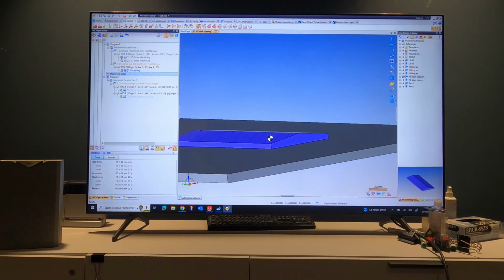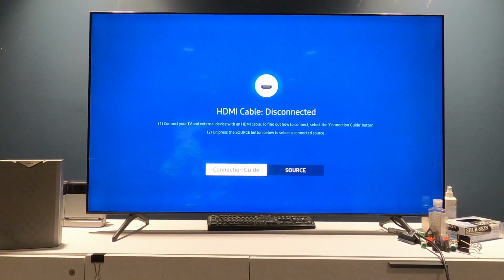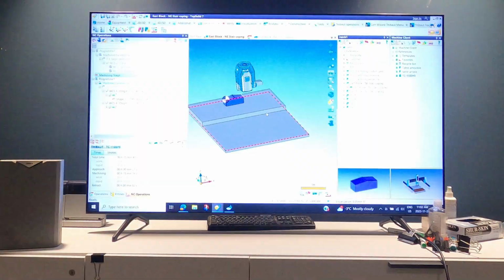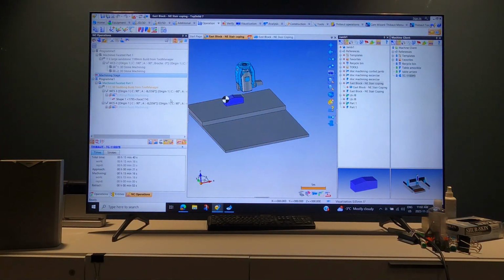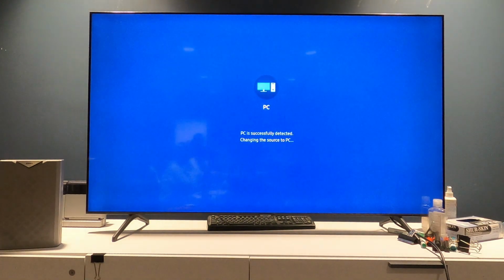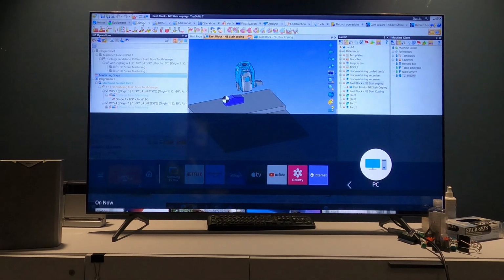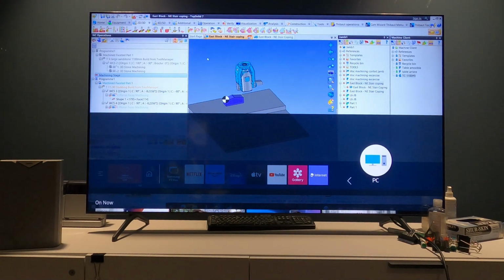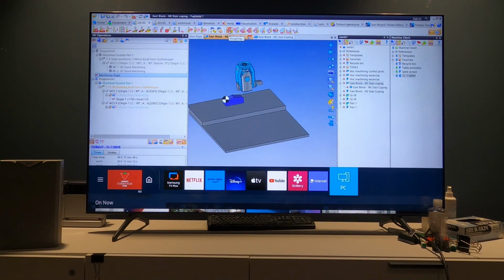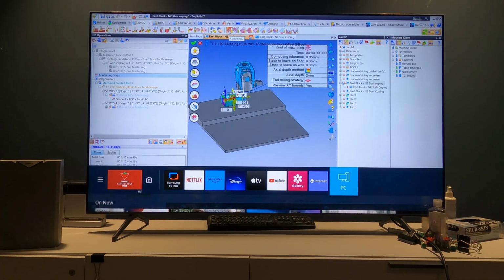Disable, yes, the first one. Delete? No. Editing, disable. Enable the safety. Okay, now bring this just before the first two pass. That's fine. So you make a roughing, 2D, 3D, roughing. You have it here. And just apply.